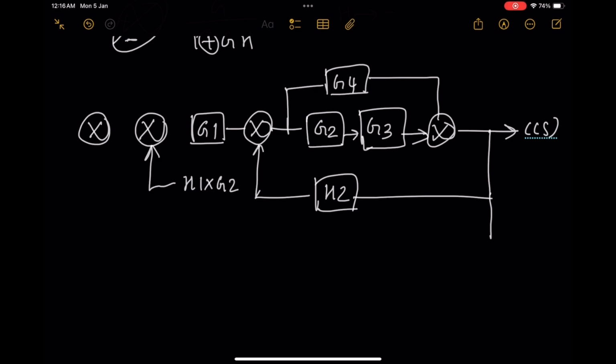Okay, I just said earlier that I'll be dividing by G2, but it's not actually division, it's actually multiplication, because the signal flowing backward here will contain G2. So if I am taking it here, it should contain G2, then only the answer will be the same. So I'm multiplying that particular equation by G2, and I'm taking it to the takeoff point here.